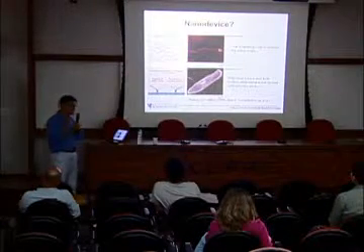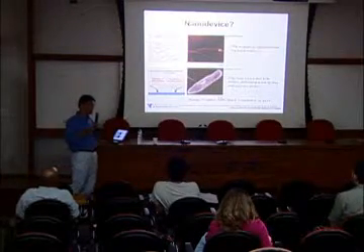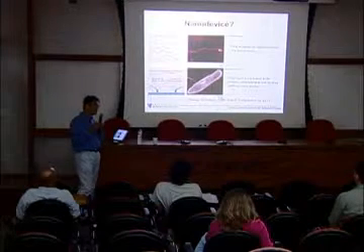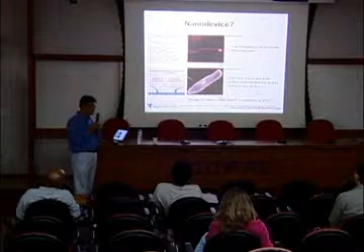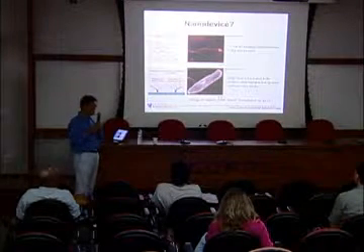It's not like water. Then, the Reynolds number at such a small scale is below 1. Then viscosity is really dominant compared with the mass. Then conventional propellers or other mechanisms do not work.